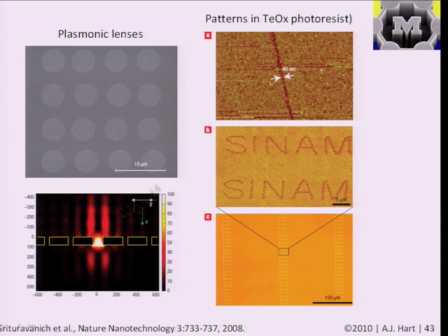And then they were able to use this apparatus to modify this special oxide photoresist, basically one that will be exposed when it gets heated up. And in fact, under this tip, things got pretty hot, and they were able to pattern lines as small as 80 nanometers. And it's just a demonstration of the ability to focus fields using this effect and to maybe combine it with some engineering to create particular patterns.